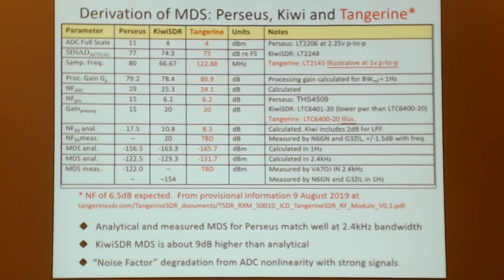Those are, basically, they have great specs, but it turns out if you take the DX Engineering board and put a terminator on the front of it and look at the output, there's all kinds of oscillation, the linear regulators oscillating at 100 kilohertz. So I had to go in, and there's an inductor right on the output of the linear regulator inside there. So I shorted out the inductor and eliminated the oscillations. But I think there's a genuine need for a really good reference, low noise, high frequency preamplifier. I couldn't find one. I mean, I'm hacking away at the DX Engineering board at this stage, it's the best I can do.